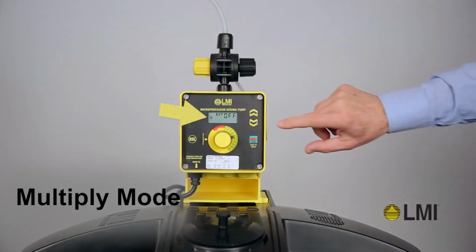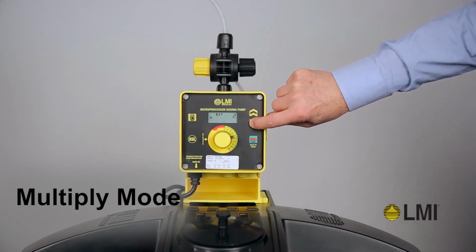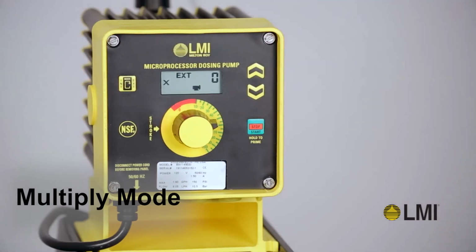When in multiply mode, use the up and down keys to change the value. The strokes per minute range in multiply mode is from 1 to 999. Press the start/stop key to start the pump. The pump symbol appears on the screen. The pump is now ready to receive external signals.